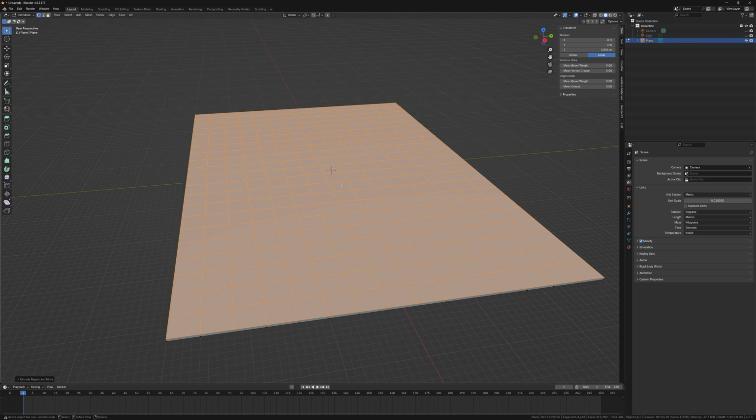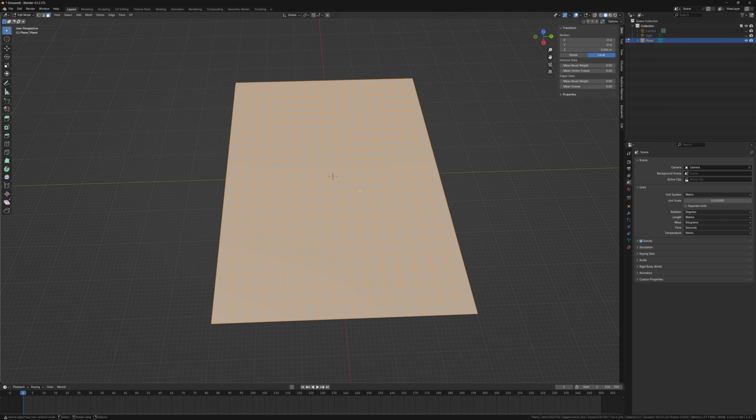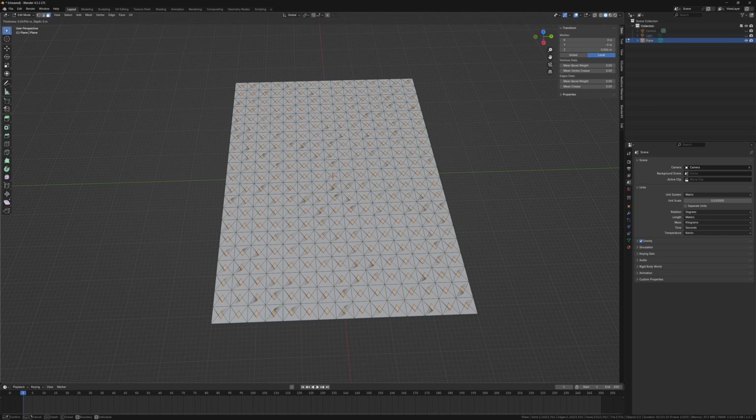Now with these items all selected, all these vertices, I'm going to hit 3. This will switch us to the faces mode. And now I can use I to inset them. Now, this is not what we want. I want an individual face inset on all the faces. So if you look here, in the bottom of my screen, the mouse keeps transferring. But in the left bottom corner of the screen, there are some hotkeys. So if you hit I once again, it goes to individual faces.